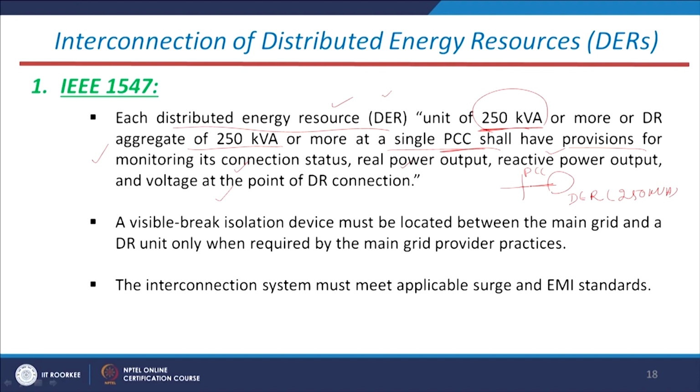This DER should have that information: how to record, how to store, and how to monitor the status of these quantities, like voltage, frequency, output power, reactive power, and active power. This DER should have that facility.